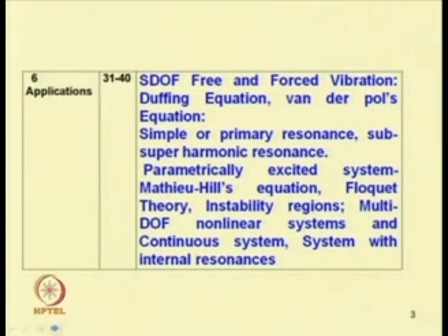We will apply the methods we have studied till now to single degree of freedom systems with free and forced vibrations. There we will discuss the Duffing equation and van der Pol equations. Also, in case of forced vibration, we will discuss simple resonance or primary resonance, then superharmonic and subharmonic resonance. Then we will study parametrically excited systems, in which we will see the Mathieu-Hill equations.